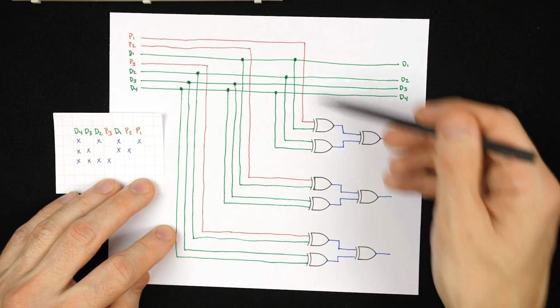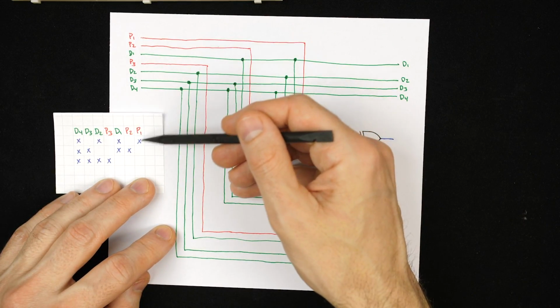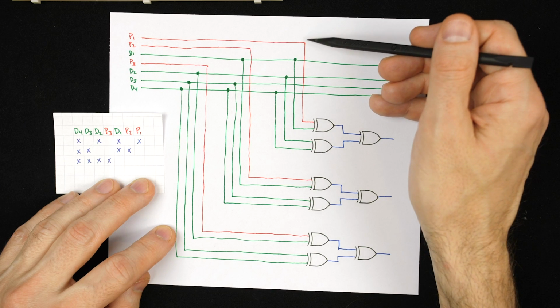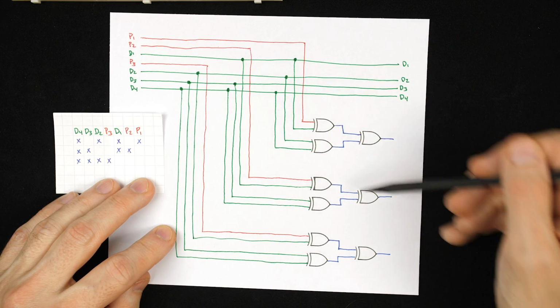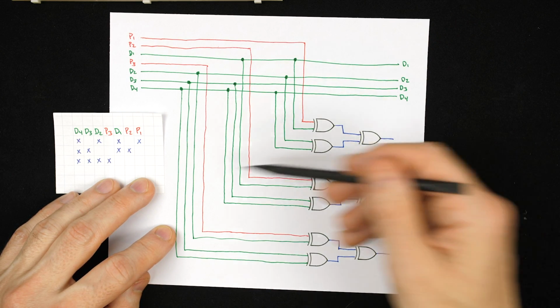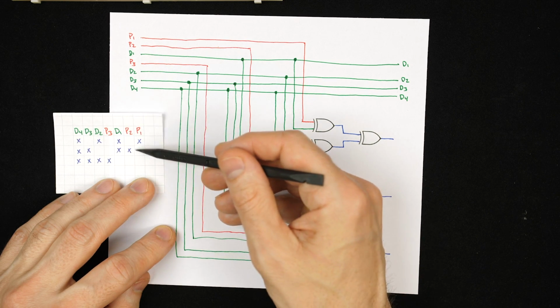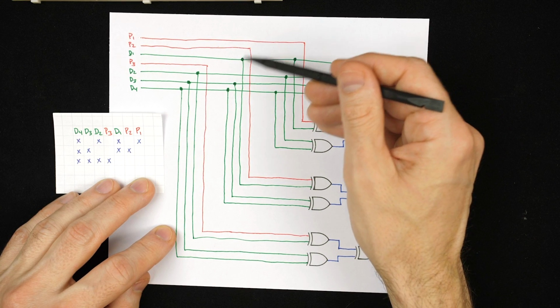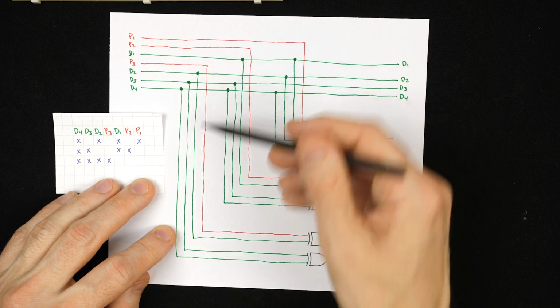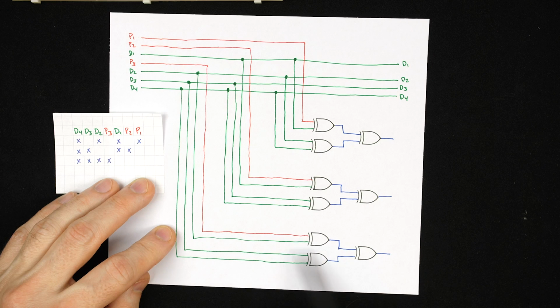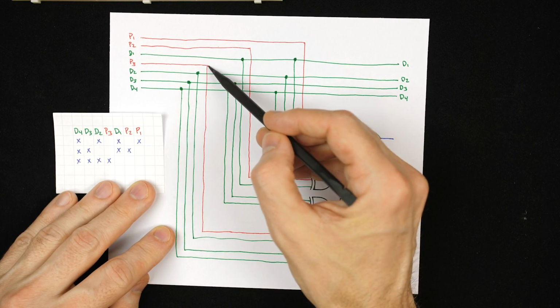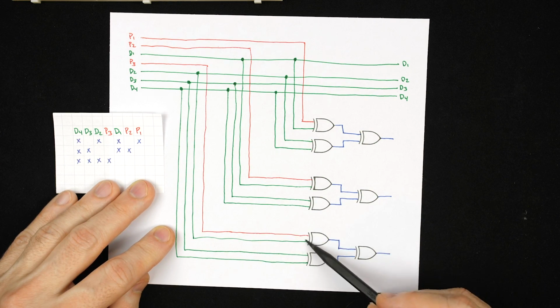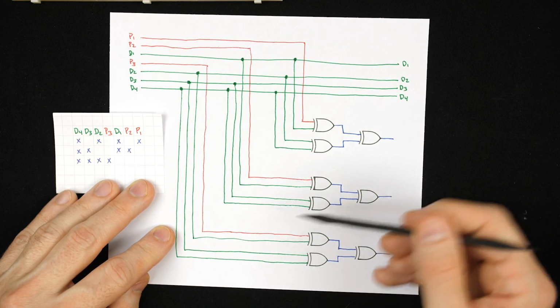And so you can see this one is hooked to every other bit. This second set of XOR gates is this set here on parity 2, and it's these 2 and these 2. You can see it's those 2 and then those 2. And then finally, parity bit 3 is coming around and hooked to these XOR gates here. And you can see it's just these 4 here. It's those 4 being XORed together. So this will compute those 3 parity bits.